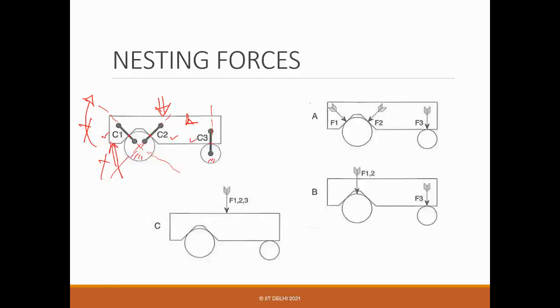So you need to find. What you see in this figure, F1, F2, and F3 are the contact forces. You can always make a free body diagram, so equal and opposite. F1, F2, F3 are the forces required, and they should be positive all the time. If the moment is negative, it means there is no contact, in the other direction it will not work. So where should the force be, so that the contact is always there?